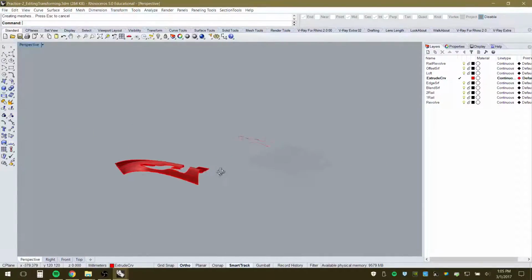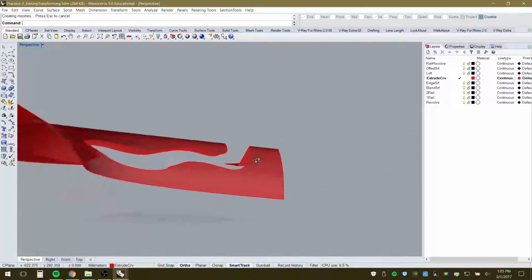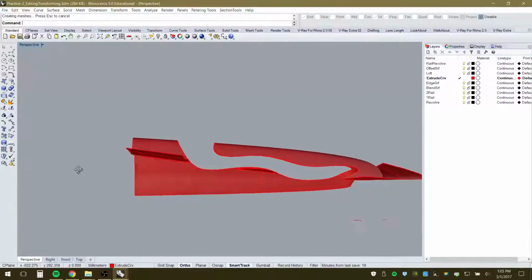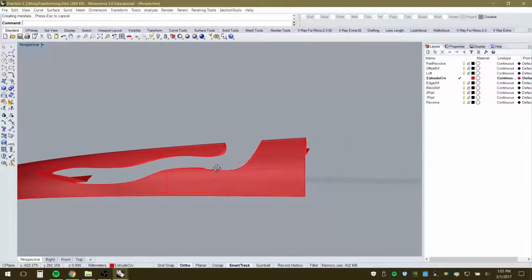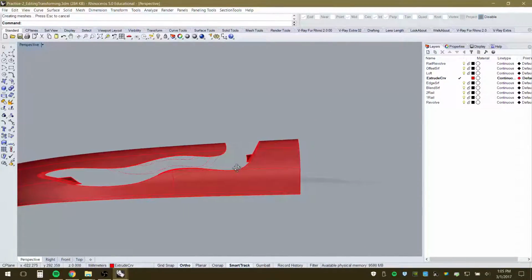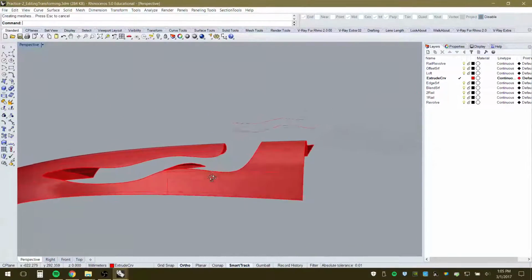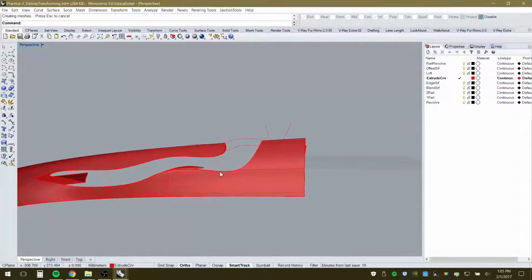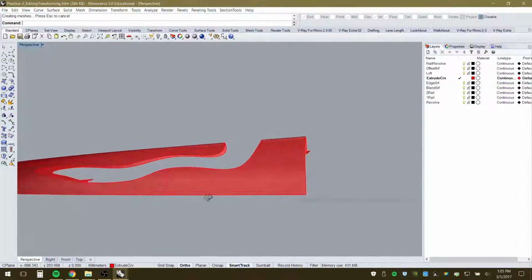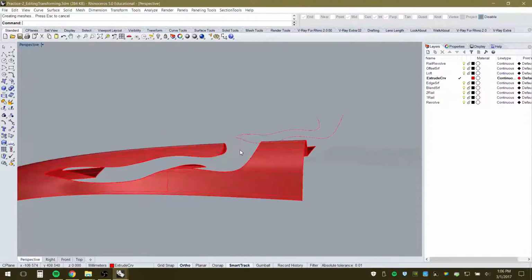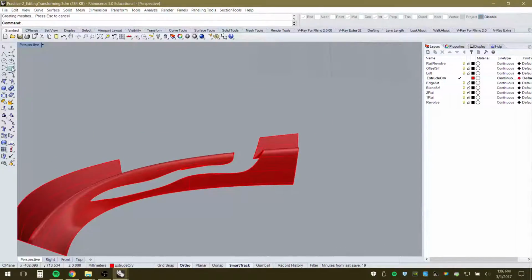If I go to the perspective view, you can see some fairly unexpected results there. But it just really simply did that, right? Trim that area right out, and just because of the orientation of the view, it knew that that's how I wanted to trim it. Didn't have to be touching or right on. I know in AutoCAD, if you want to trim that way, those objects have to be coplanar, essentially. These don't have to do that. You just have to be in the right orientation in a view, and you can execute the command. And that's true for perspective and for any of the other views.